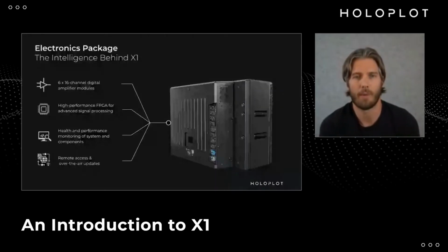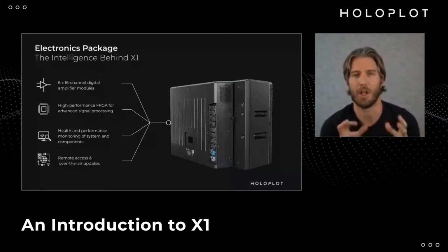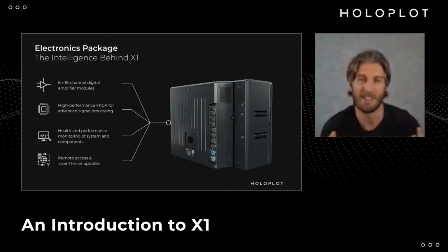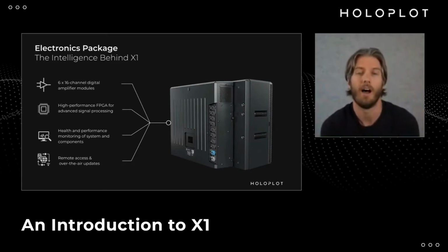So what kind of makes all this work? What's the kind of magic that sits in behind this? And this is the electronics package. This is the intelligence that sits behind the unit and actually ensures that all of these drivers work together. So each of the drivers is individually amplified and DSP processed. There is an FPGA, which is a field programmable gate array, that's handling the signal processing. It's a decentralized processing system in that respect. So there's no supercomputer that sits at front of house doing all the processing here. Everything is actually done on board of the unit.